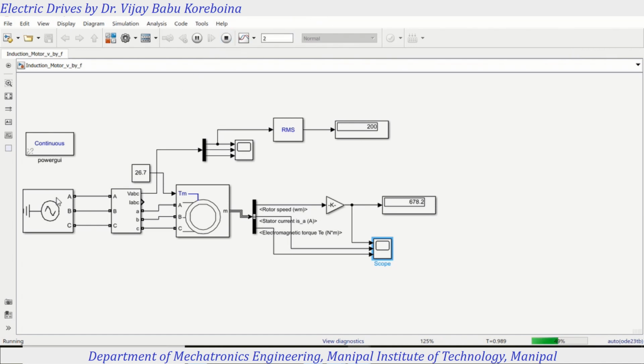So that's why we are changing the voltage as well as the frequency. That is the meaning of V by F control, and we can have the maximum torque with V by F control. The flux is maintained. These are the things that we can see from the scalar control. So stop here. Now let us put one question.